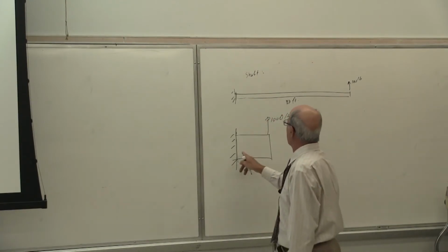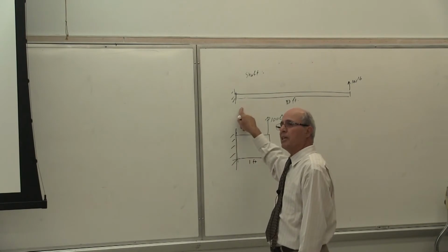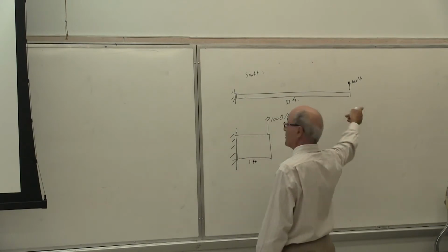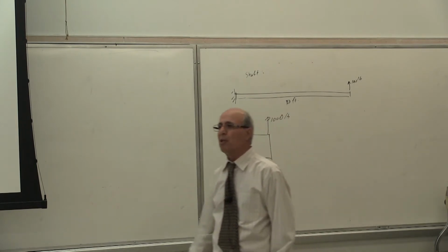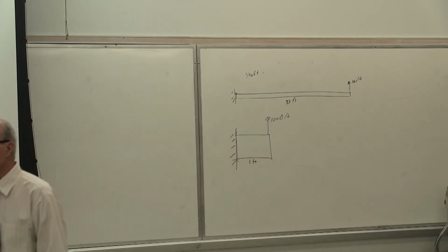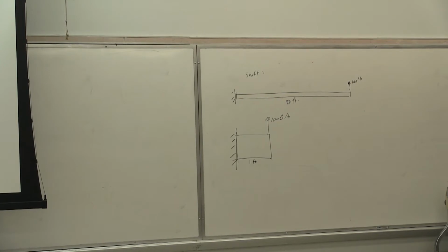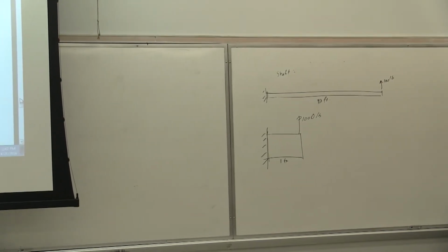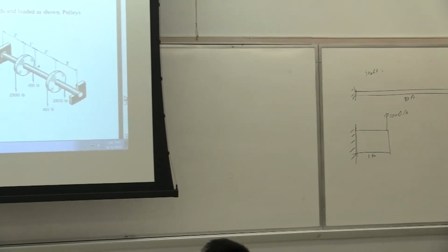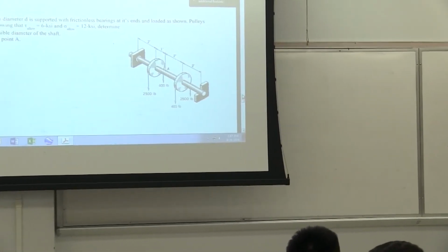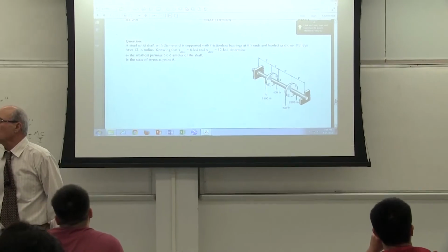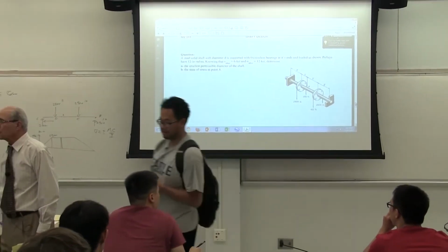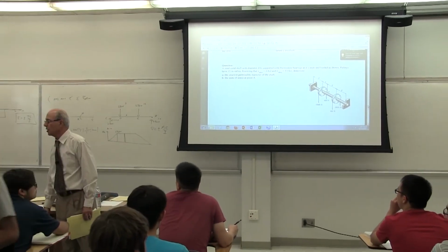But here, there is a larger shear value. Here, there is less shear because the distance, everybody, here the distance is larger. Force, of course, is smaller. Since force is smaller, shear value is smaller. So TC over J will give you, let's say, 7,000 PSI, 10,000 PSI. I have an example later on that I'll show you. That one shows you 30 PSI or 50 PSI compared to VQ over IT that I'm talking about.